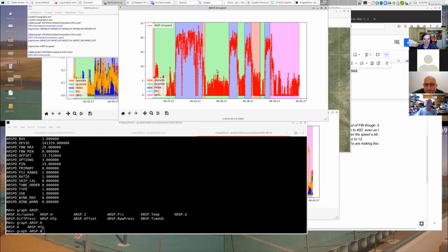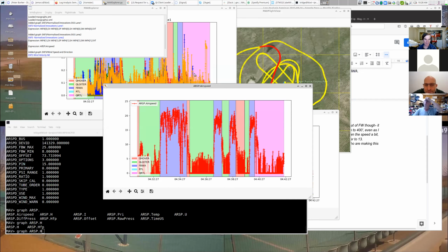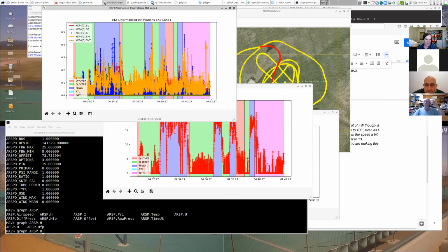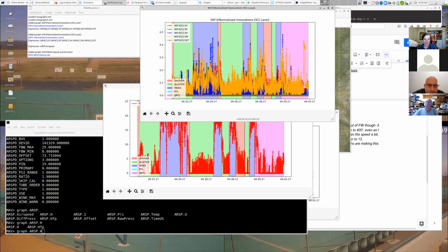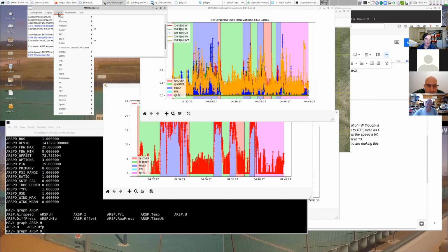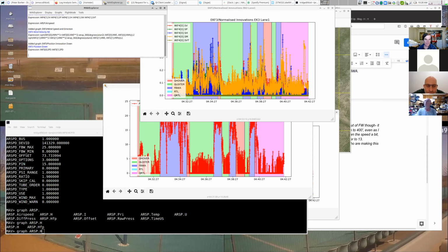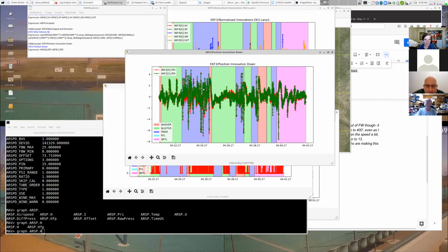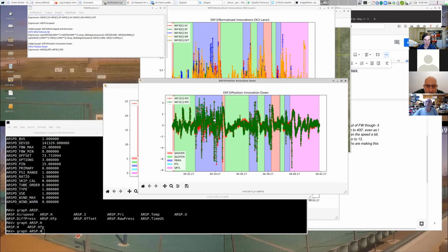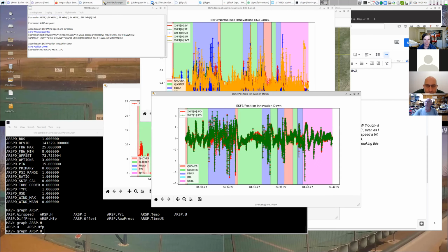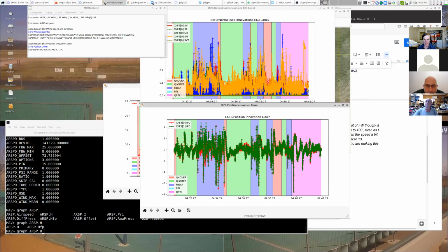So interesting that bug shows up. Apart from that, we're seeing a little bit of magnetometer error, a little bit of height innovation here, and we could have a look at how significant that is in terms of the actual position down innovation. All right, we're seeing the height innovation noise here of like 5 or 6 meters, quite high, and that's sitting in fly-by-wire array. So we're probably getting a little bit of sort of Venturi effect and noise as well.